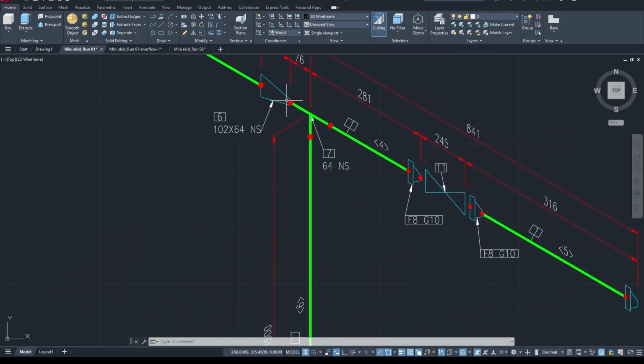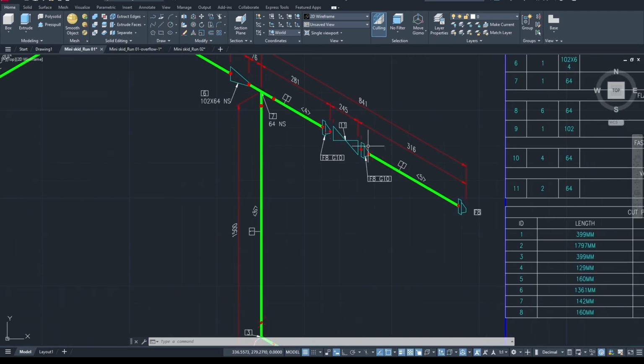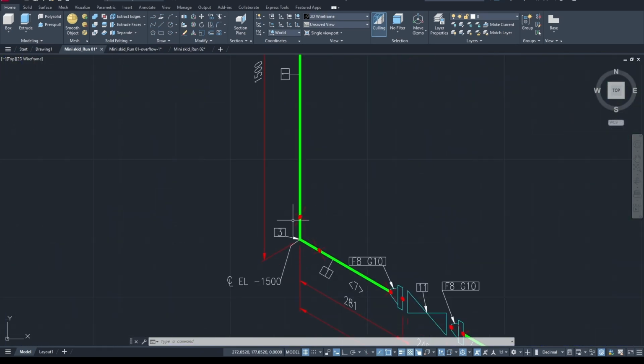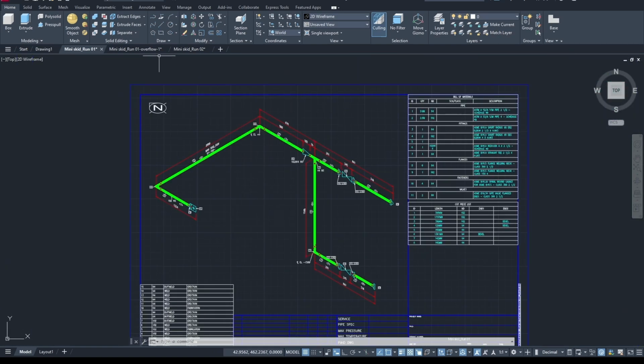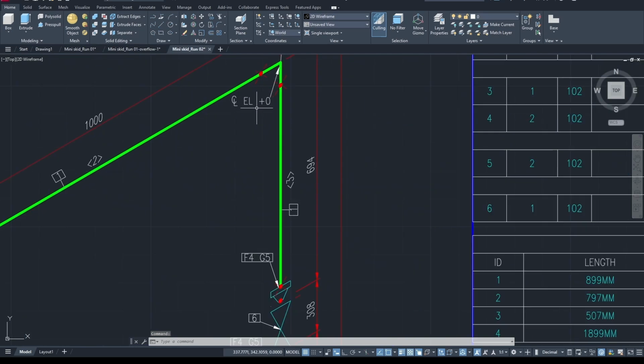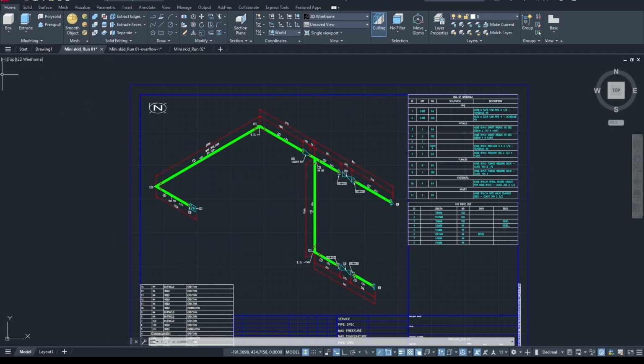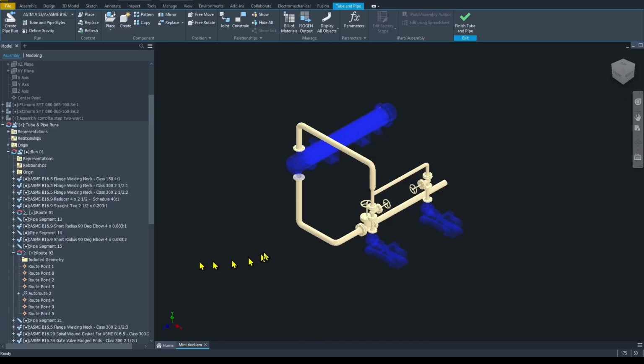Next, some flanges are improperly oriented and bolt annotations are missing. We can only see the flange and gasket annotations. A similar issue is present in another drawing. However, the main problem, which is not immediately obvious, lies in the orientation of the isometric drawings. Pay attention to the coordinate system in which the model is drawn. The XY plane is vertical, meaning that north is vertical since it always aligns with the y-axis.